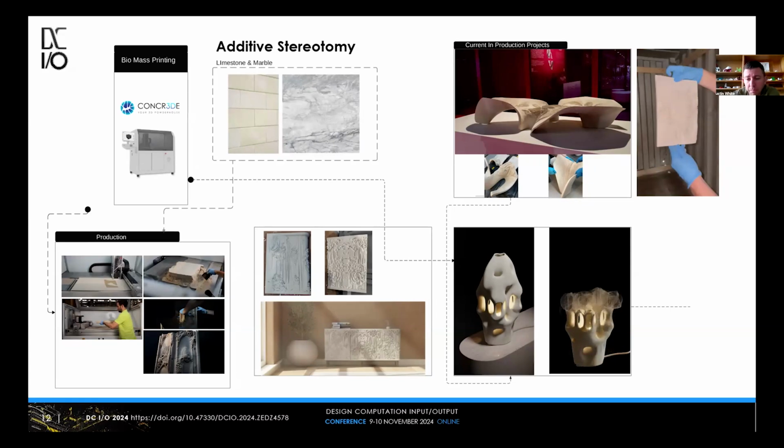Concrete specializes in binder jetting technology, a 3D printing technique where successive thin layers of powder are deposited within a machine. For each layer, a binder is selectively jetted to form a cross-section of the 3D model. At the end of the process, a solid printed shape emerges, encased in loose powder that wasn't bonded during printing. After retrieving the printed part, the excess powder is removed for reuse, resulting in a zero waste process.